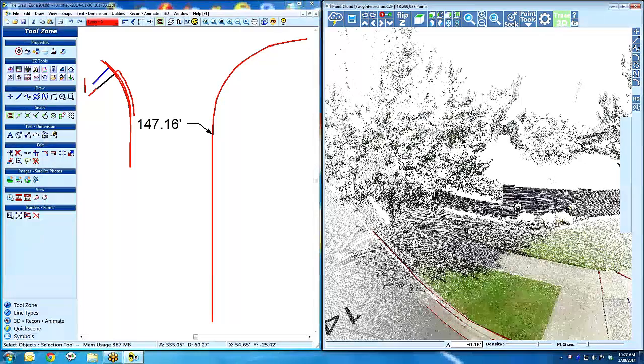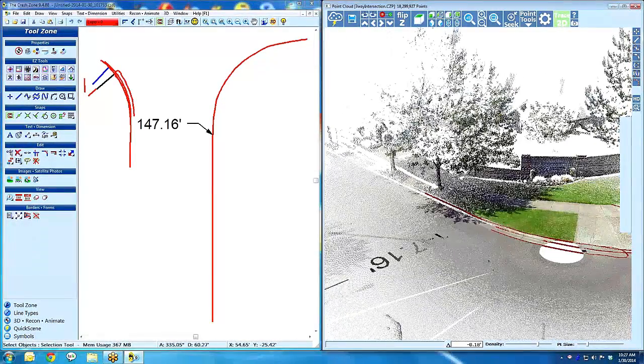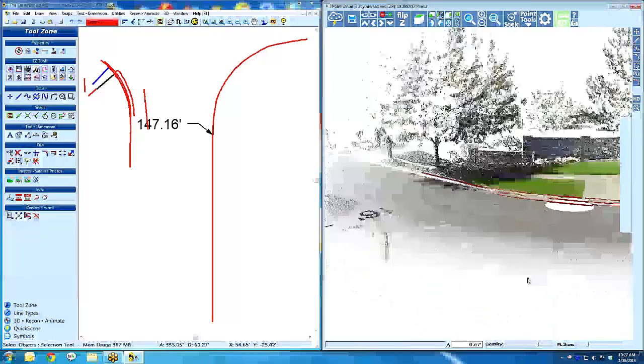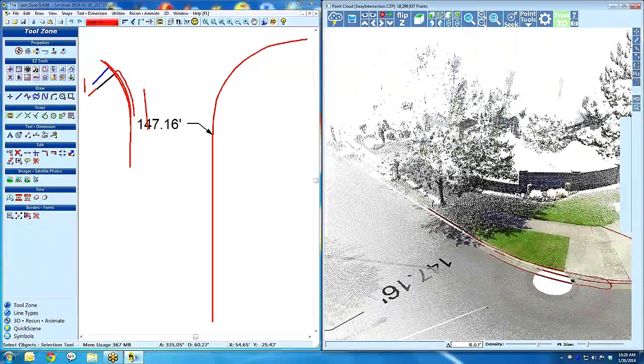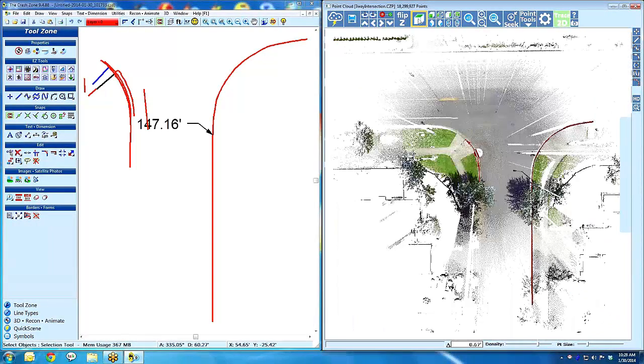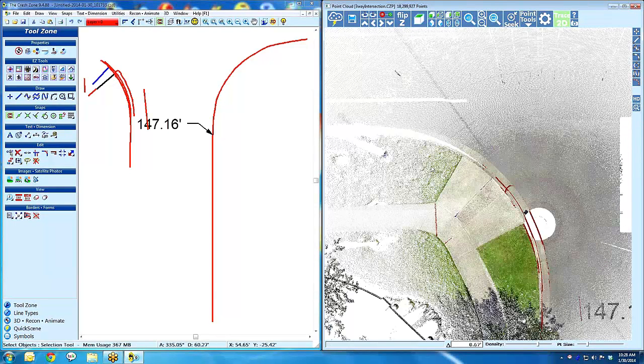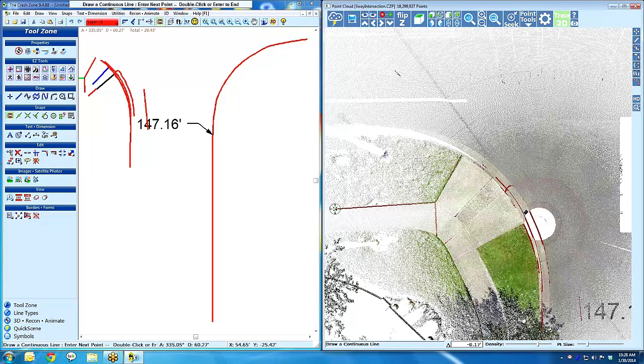And what happens is no matter where you click in the cloud, if I draw a line from here to here, it does snap to these points, but it goes all the way to the 0 level. That doesn't make a bunch of 3D lines or slopes or anything. So you go into 2D trace mode, go into top-down view, maybe zoom in on an area you want to draw, and it's very easy. You're still snapping to the real world points. You're getting nice, accurate drawings.